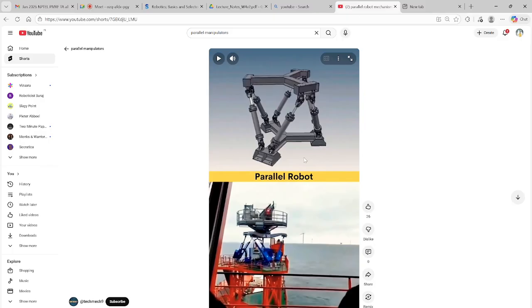So here we have a video of a parallel manipulator. Initially we had seen what serial manipulators and parallel manipulators are, right? A serial manipulator is basically a connection of links, and at the end we have an end effector. But in this case, we look at a particular base, and any one of the links can be the end effector, for which we want a certain position and configuration. It can be defined corresponding to a particular link, but there is no fixed end; there is a fixed base, and then there is a mobile base. If I play this video, you can see it.